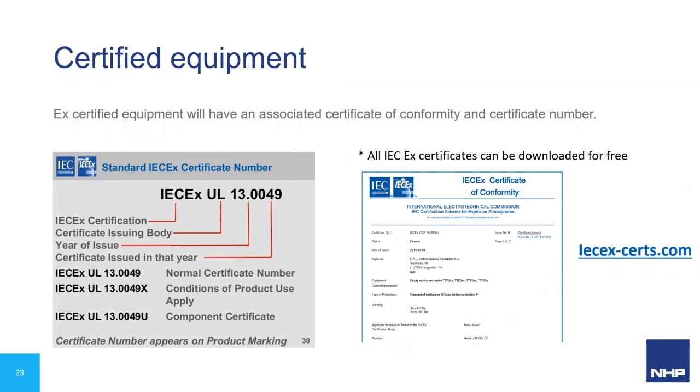Now, all Ex certified equipment will have a certificate of conformity, and the end user will need this certificate as part of their hazardous area verification dossier on site. The IEC certificate number is printed on all certified equipment and is made up of a few bits of information. So you can see there, first you have IECEx. This is the certification that's accepted for use within Australia.